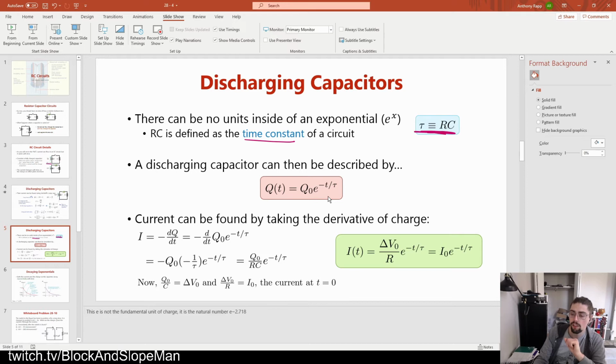So when I plug all of these things in, right, and here's my argument about taking Q and plug it into delta V and then plug it into our circuit, we find that not only does the charge have a dependence, e to the negative t over tau, but so too does the current. In the exact same relationship, in fact, right? E to the negative t over tau. Both of those, depending on that initial value that we started with, and then decays down from that.